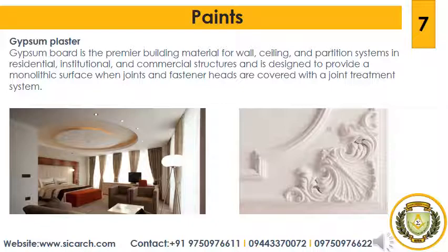On heating further up to a temperature of about 200 degrees centigrade, the entire water of crystallization is driven off and the resulting product is known as gypsum anhydrite or hard burnt plaster. The setting time of gypsum anhydrite is more and to shorten it, the accelerators are used. The common accelerators are alum, potassium sulfate and raw gypsum. The term anhydrous gypsum plaster is used to indicate the gypsum anhydrite with accelerators. So next we will see the properties and uses of gypsum plaster.